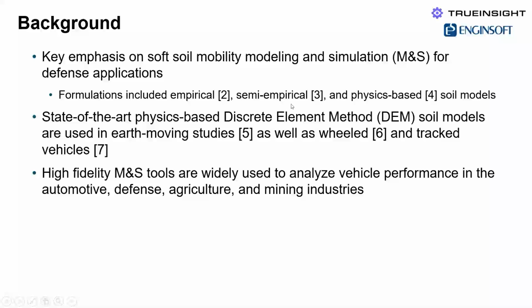Empirical models, semi-empirical models, and then physics-based soil models like what we're talking about with EDEM. So really, the current state of the art is to apply discrete element method technology to study the behavior of the vehicles and their interactions with the soil. And that can apply to both wheeled vehicles and tracked vehicles.